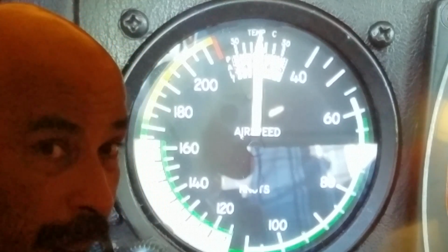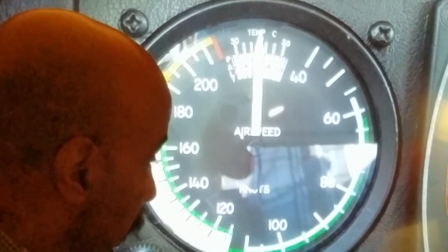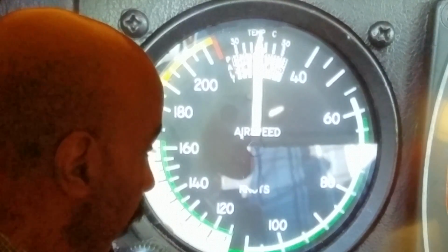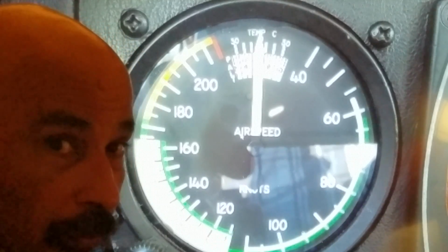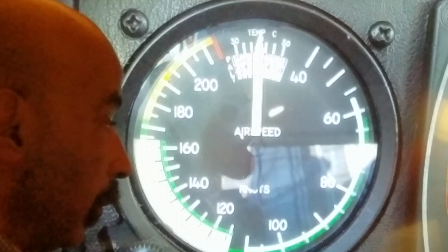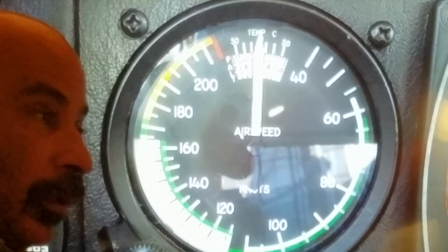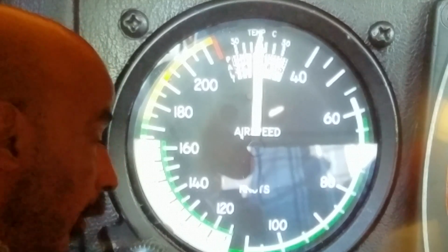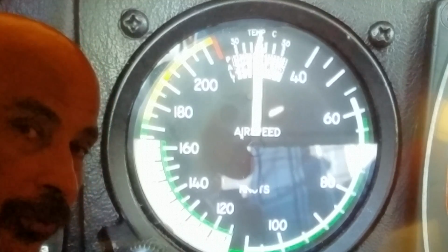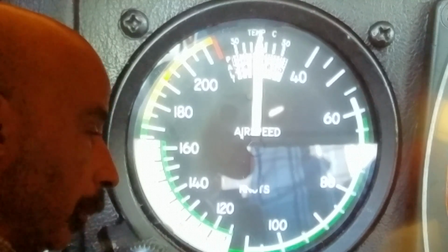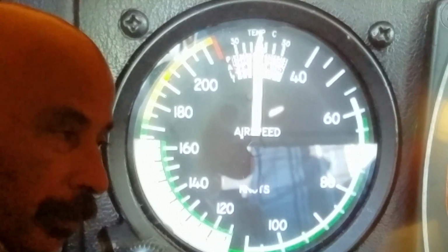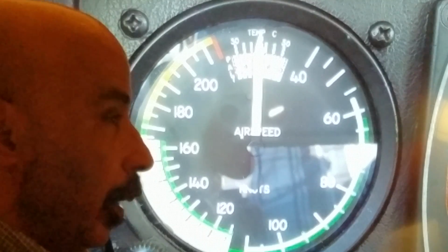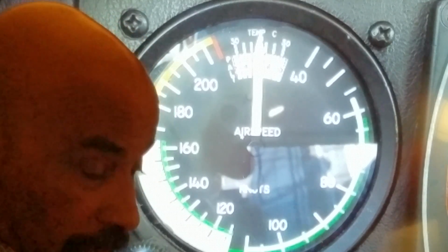Another airspeed is called calibrated airspeed. Calibrated airspeed is indicated airspeed corrected for position error, meaning that if the pitot tube, which is the probe that sticks forward in the airstream, is at such a distance from the airspeed indicator, and the long tube coming up to the airspeed indicator from that pitot tube causes a certain amount of air pressure drop, then that position error is what they're naming calibrated airspeed.